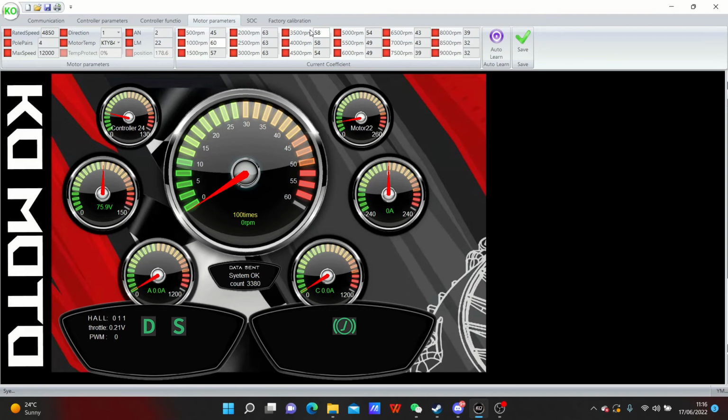You can change this value from 0 to 100 effectively, but we don't recommend changing it to anything less than 20, otherwise you will potentially have some problems. And if you set everything to 100, you may also have some potential problems with motor shudder or drivetrain shudder. What you need to do at this point is to understand that if you set everything to 100, your drivetrain on your bike may not tolerate this. So it is a case of finding a happy medium and finding what your drivetrain will tolerate. So this will require some tweaks and some tuning.